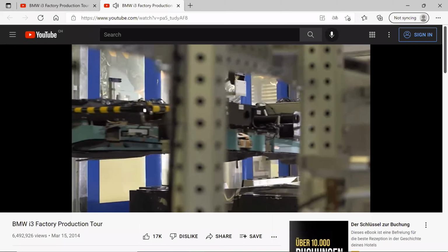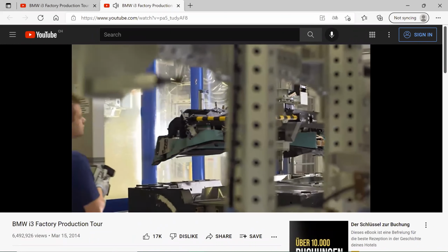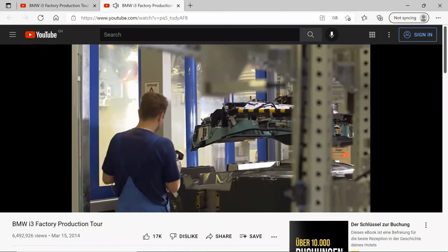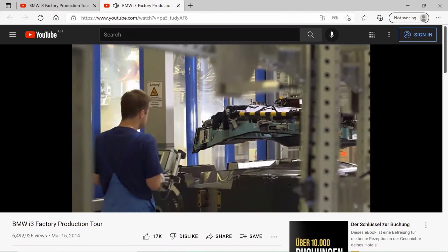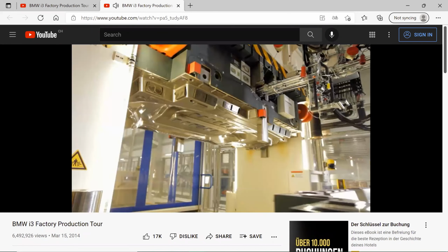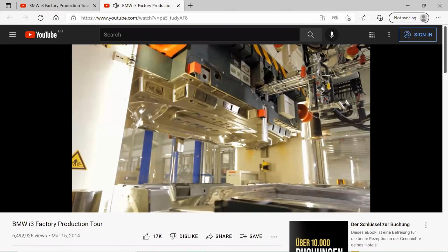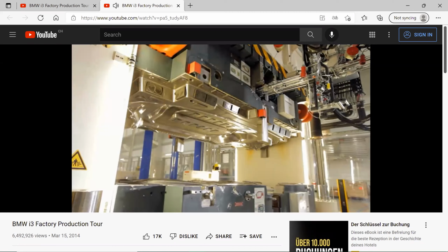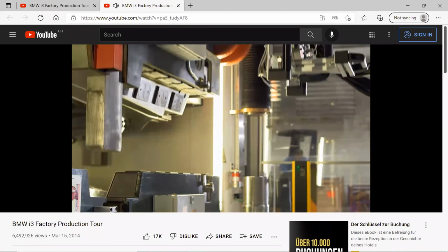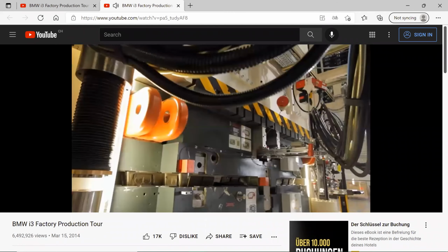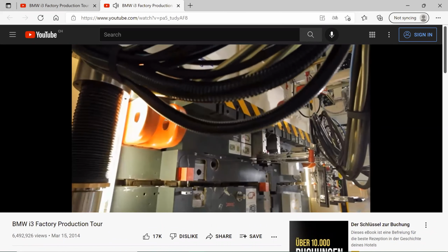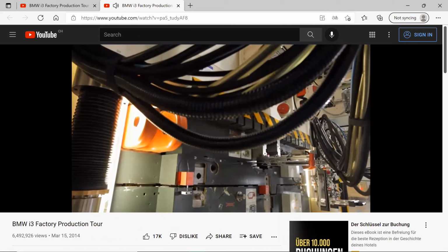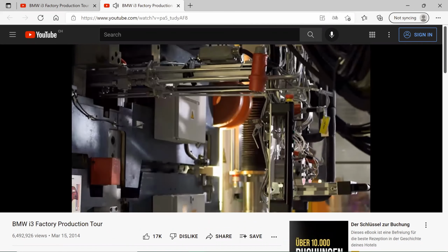Picked up, it's placed in the Schuler press. So you can see it's slower than a thermoplastic, but very automated, very big press. And now the high pressure RTM process in general is around 40 bar, about 3-minute cycle time.